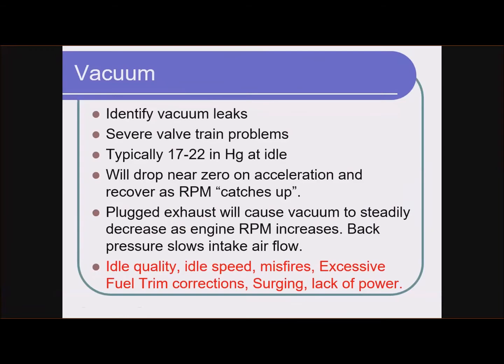Possibly late valve timing could do the same thing, right? If the valves are not opening and closing at the right time, it's affecting how well the engine breathes, which obviously is going to show up on a vacuum gauge.